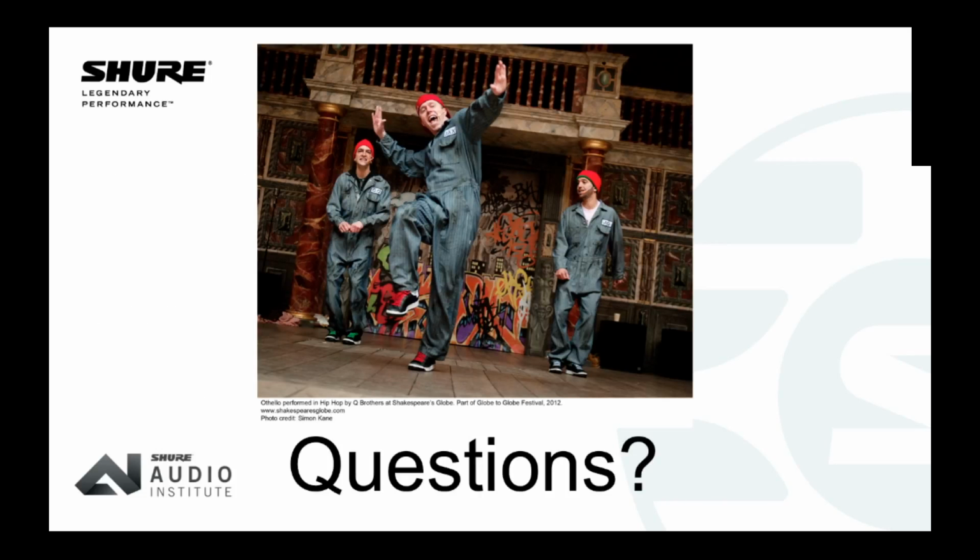All right. First question here. Can you effectively run a WL93 as a four-head mic versus the B3 type mics that we saw in the illustrations? So the WL93, for those who don't know, is one of the more inexpensive omnidirectional lavs that Shure has, and yes, you can do this. It's still omni, so it's more of a rectangular flat thing instead of the round ones, but the concept is the same. There's a little opening on one side of it. Don't push that part against the forehead. You'd want to make sure that's facing away from the forehead, but otherwise I think that would work.